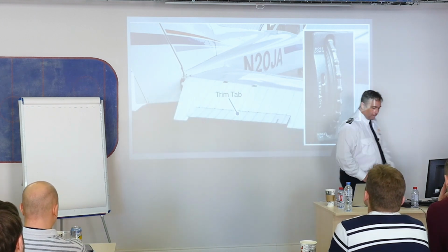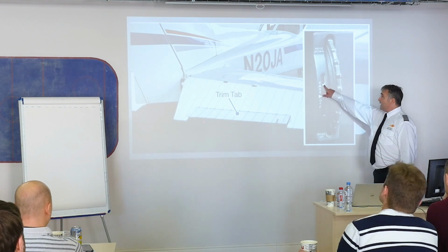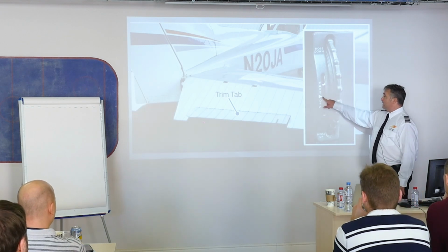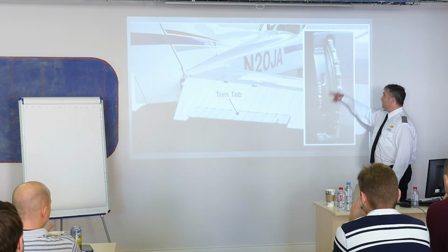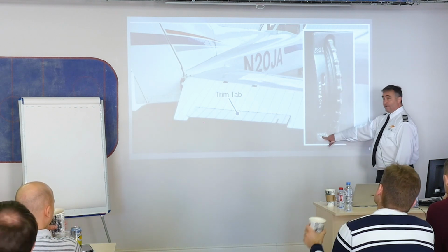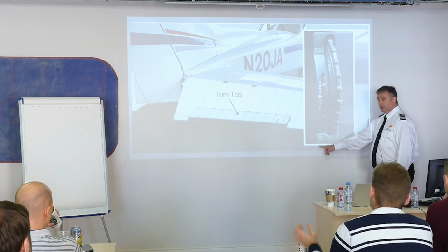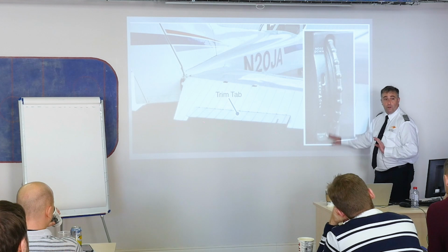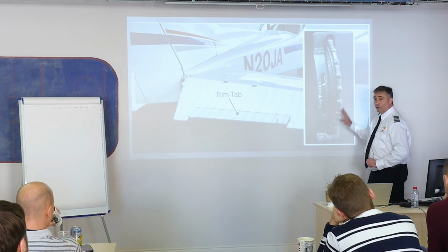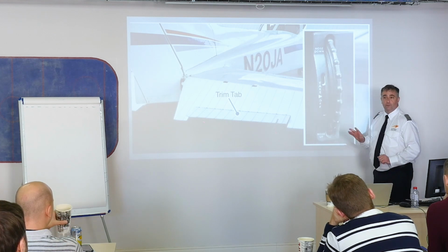And this is exactly what it looks like in the airplane. You've got a neutral setting here. It'll show you how to set for takeoff. You put it right there on that index mark. You just roll down like that. That makes the nose go up. You push the wheel down, that will trim the nose up. If I push the nose forward, that trims the nose down.